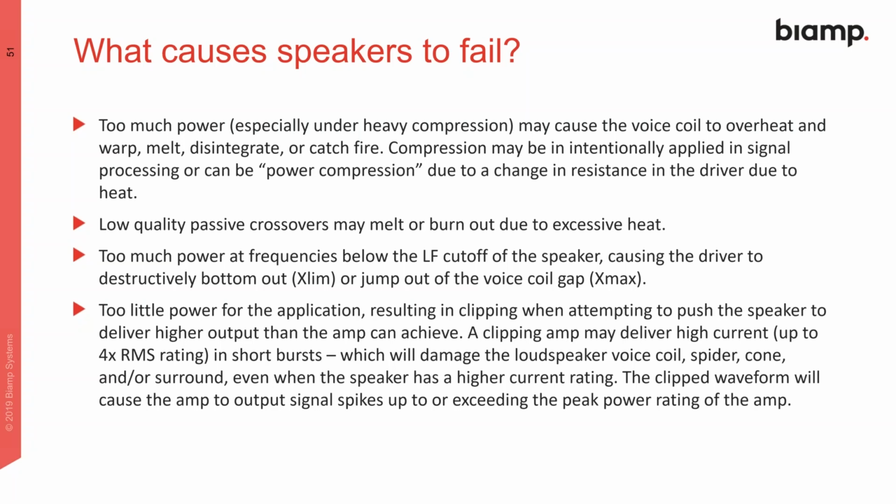It's trying to start and stop the motor very quickly, and it can cause it to arc and disintegrate. Too much power can cause things to just straight up melt in crossovers and things like that. But also too little power, if you're driving an underpowered amp, and so it's constantly driving into clip, you're going to get weird harmonics through the system. You're going to get irregularities. Instead of a nice push-pull method, it's a jackhammer type method, and that is just going to destroy the driver. So there's a number of things that can cause those to fail over time.